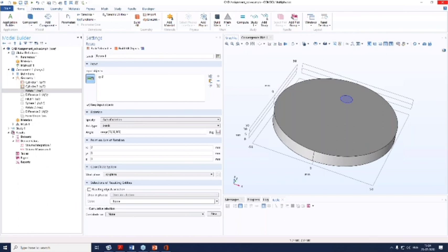In the given assignment, how can I perform the copy operation as I want them in a circular manner? As I mentioned earlier as well, rather than using the copy feature, you will need to use this rotate feature in order to get the circular array effectively.